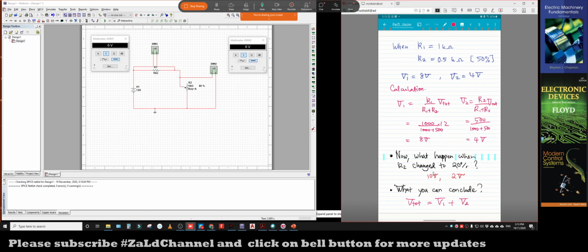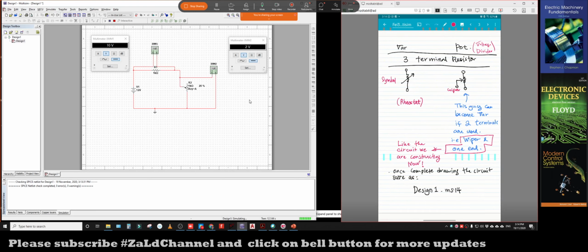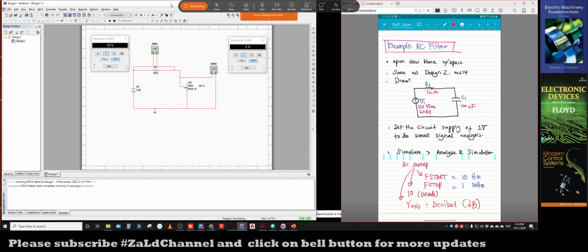So what happened when we change to 20%? Either you can do the simulation again and then check on the voltage. When we change this to 20%, we have 10 volt across R1 and 2 volt across R2. So we can conclude that the total voltage here is equal to the voltage here plus the voltage here, which is the voltage across R1 plus voltage across R2. So that sort of thing is the explanation about our first circuit. All right, so now we are going to move on.